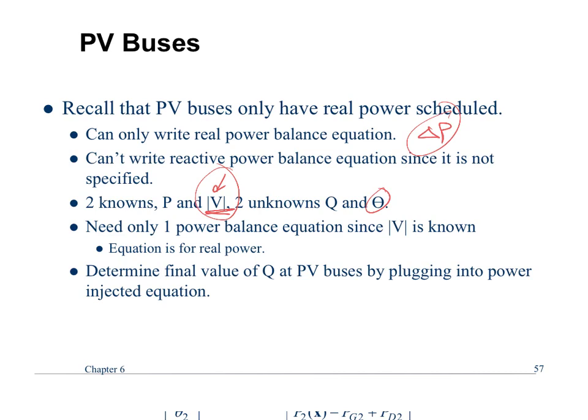And if you remember when we partitioned our Jacobian matrix, here's our delta P's and then our delta Q's, and our thetas and our V's. When we partition our matrix, our theta is primarily going to be determined by real power flow, right? We talked about that from the transmission line operation. So in sensitivity analysis, real power flows tend to be far more sensitive to theta changes than to voltage changes.